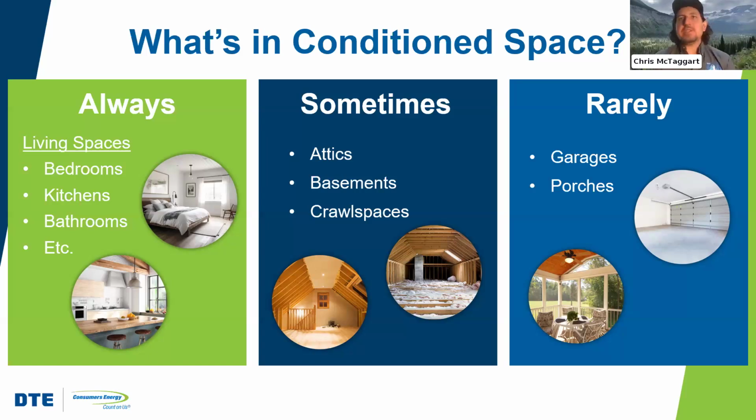Crawl spaces, I would say we are increasingly moving towards having crawl spaces that are within the conditioned space. We are insulating and sealing at our crawl space walls. Not necessarily always the case, but there's a lot of benefits for sealed crawl spaces. We talked about that in the last couple webinars. We don't need to talk about that a whole lot more because it doesn't pertain all that much to fenestration. Rarely, but sometimes, garages and porches are considered conditioned space. More often than not, they are unconditioned spaces that are not part of our building thermal envelope.